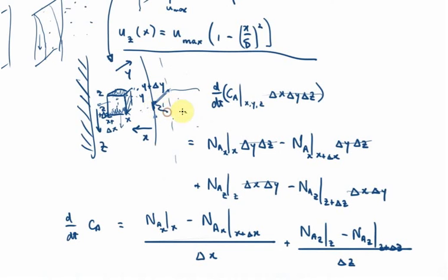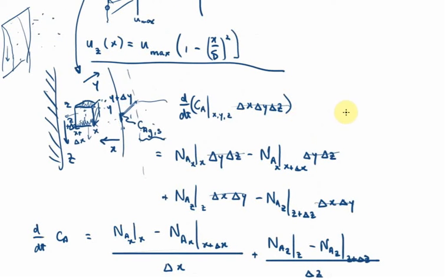So let's write this as Ca in the gas on the surface, or rather the gas immediately next to the surface of the film. So if it's defined like that, then we might have some equilibrium relationship. So if we have the gas-liquid equilibrium constant of component A, right, so let's say that equilibrium constant is simply K, then we might be able to say something like Ca gas surface times K. That will give us Ca in the liquid on the surface.